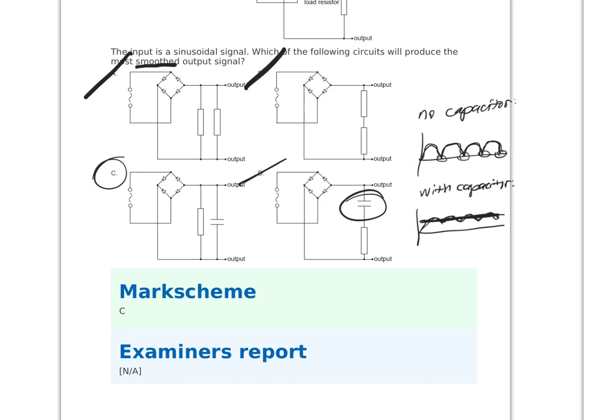Whereas if you wire the resistor and the capacitor in parallel, while the capacitor is loading, you still have a complete circuit because there is a load in parallel with it. So you wind up with C being the legit setup and not D. You want your capacitor in parallel with your load, not in series with it.